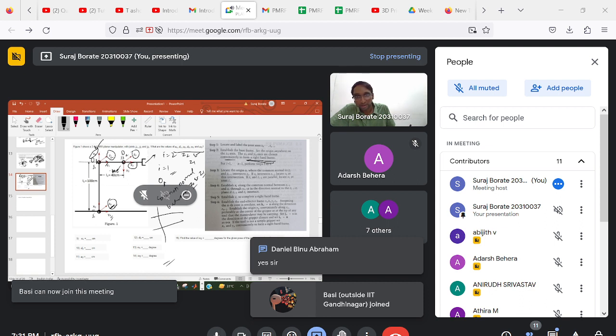Now we have x2 along the common normal, and we complete the right hand rule. We choose y such that the right hand rule is completed, so y2 will be here. So it is also correct. And now we just copy this frame here to get the end effector frame. So this is z3, y3 and x3. Fine, this is how we label it.